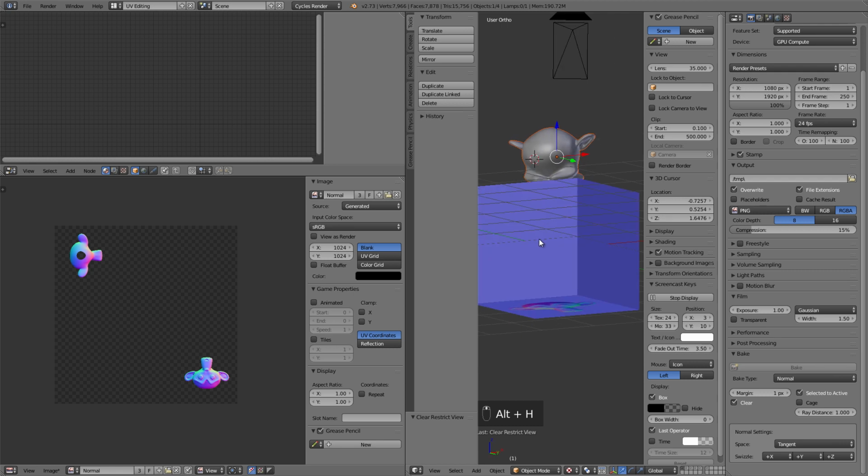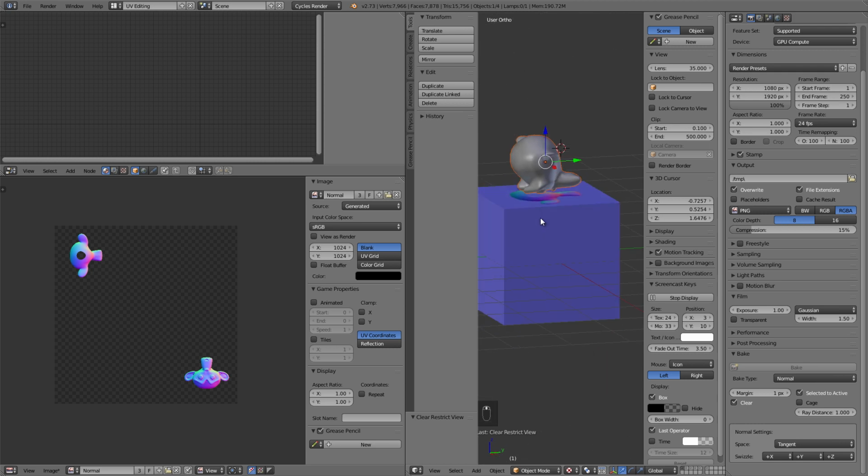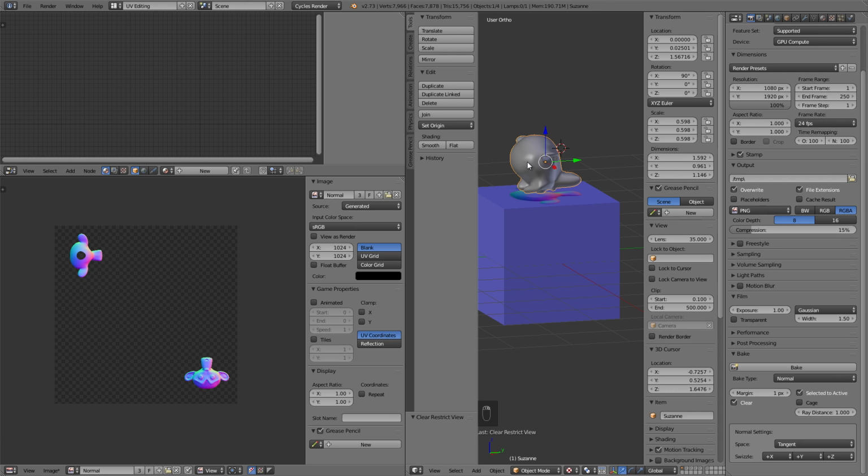This method is most suitable in Blender Internal, so if you want to surround your object with other objects which kind of imprint this like a stencil, then I'd strongly suggest using Blender Internal, because in Cycles it's much more suitable to do basically the opposite.